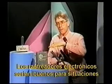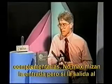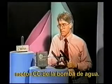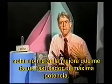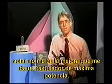Electronic trackers would be good for sort of a complementary situation. They don't maximize input, but they maximize output to my DC motors and my water pumps. If I have conditions of low insolation due to overcast, cloudy skies or foggy skies, a sun tracking system won't give me the enhancement that a maximum power tracker will.